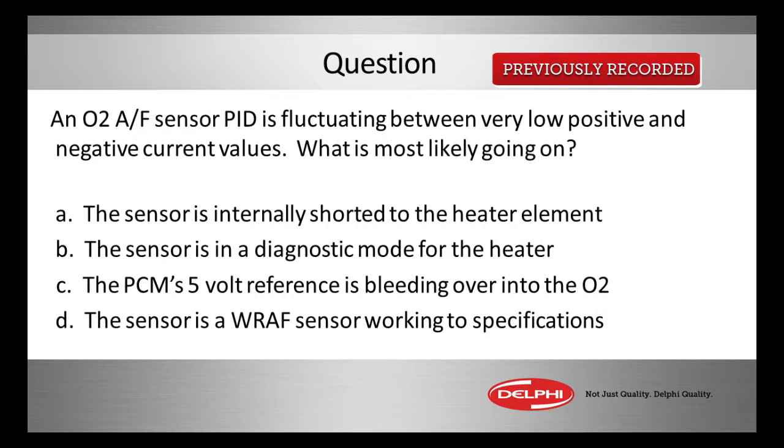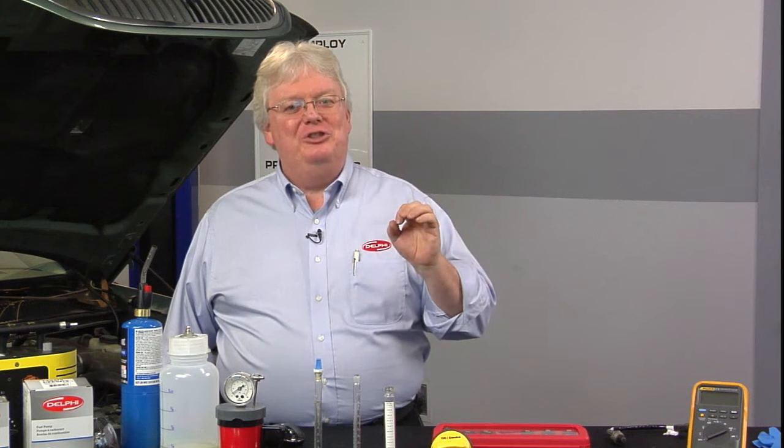Now, here's another question for you. Speaking of those new style of O2 sensors, sometimes called wide range, sometimes called air fuel sensors, regardless, they're not a switching sensor, which is either saying rich or lean. It doesn't really tell you how rich or lean it is, but those have been the O2 sensors since the 1980s, and they're still used behind catalytic converters, but most cars have switched, not all, but most, to a different type of sensor. In the video, you saw a PID value for the pre-cat sensors for oxygen. What did those sensors do?